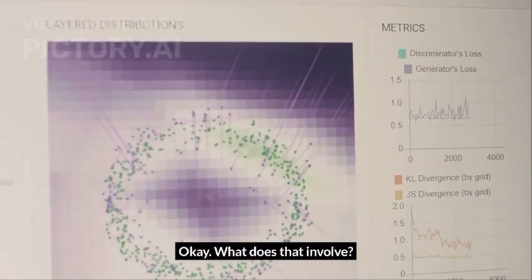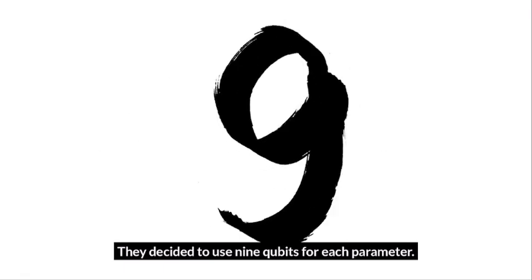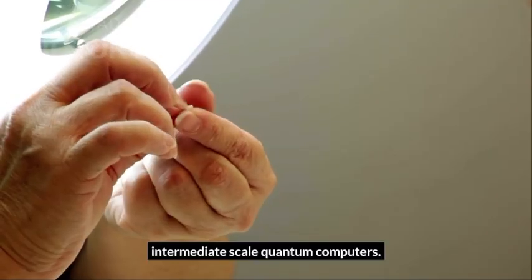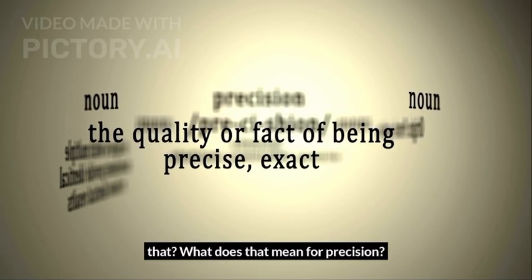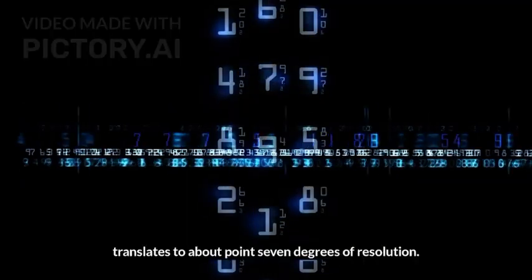Okay, what does that involve? You have to take the continuous values, like joint angles, and turn them into discrete steps that qubits can represent. They decided to use 9 qubits for each parameter. That was a practical choice for today's NISQ, noisy intermediate-scale quantum, computers. 9 qubits. How fine-grained is that? What does that mean for precision? It gives you 512 discrete values per parameter. For angles, that translates to about 0.7 degrees of resolution.